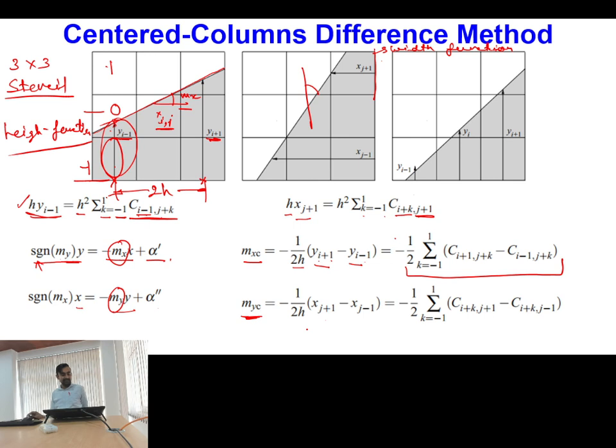Okay, but this cell-centered approach has one limitation. What is the limitation? Earlier I told you one important point, I highlighted it 2 times. Now you will understand the reason. I told you when using the PLIC, we will be reconstructing the interface profile. Either that PLIC line segment can cross the interface at opposite cell boundaries, or it can cross at adjacent cell boundaries.